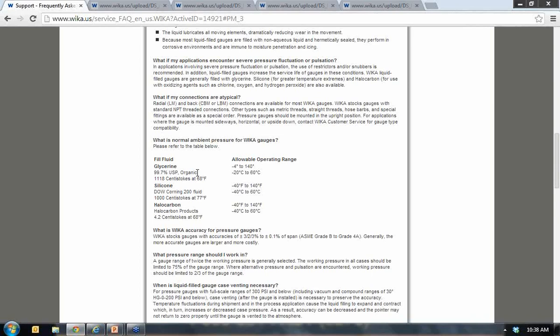You should put a volume of water inside of that pigtail before installing the gauge, and that's going to separate your gauge from the steam. Now that serves two purposes. Number one, it's going to cool the hot steam before it reaches the pressure gauge, and the airspace above that liquid volume inside of the pigtail will dissipate the temperature. And number two, it also prevents water hammer, which is very prevalent in steam applications, from actually reaching the gauge and damaging the gauge from pressure spike. So that is what the pigtail siphon is intended to do.